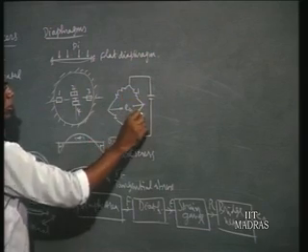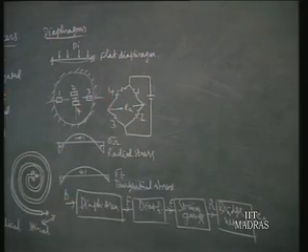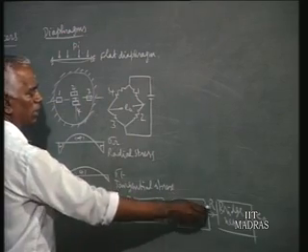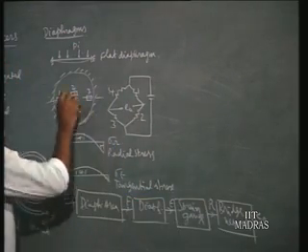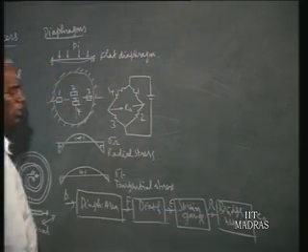So this is 1, 2, 3, 4. 1 and 3 compressive, 2 and 4 tensile. This gives the maximum sensitivity for the bridge network. The strain epsilon produced is picked up by the strain gauge, and R is changed. So the resistance of the strain gauge is changed, and then we get an output from the bridge network.